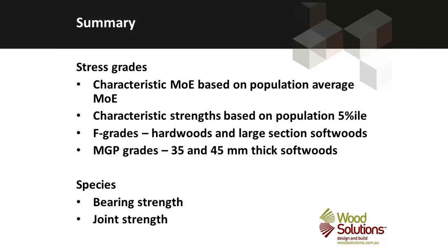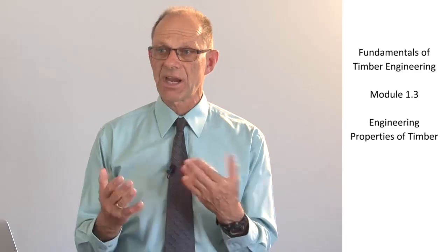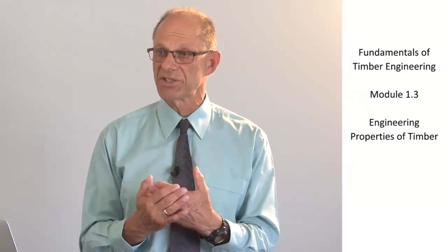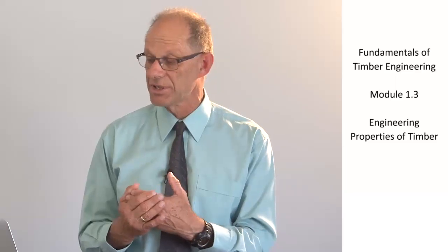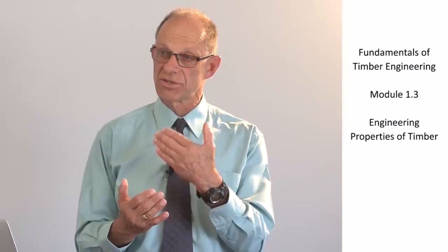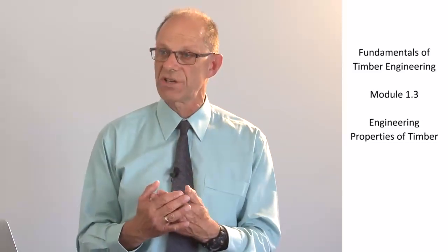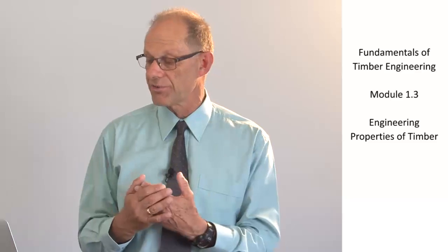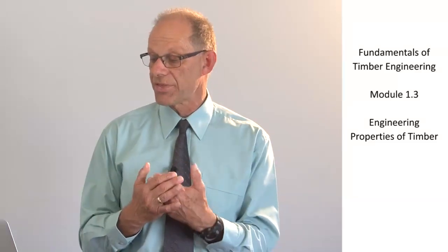So in summary, stress grades are awarded in the production of structural timber elements. Those stress grades can be used to relate the structural timber to its characteristic strengths and its characteristic modulus of elasticity. The characteristic modulus of elasticity published for every structural timber element is based on its average, and the characteristic strengths are based on the 5th percentile.